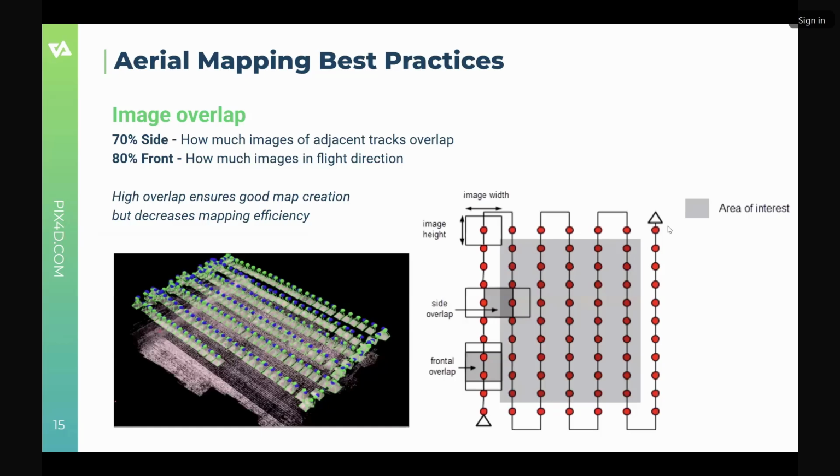So this is a really important parameter. It's the image overlap. Basically, if you want to stitch a map like we do, like what we call an HD map or an ortho mosaic, the images need overlap because, I mean, you can't really stitch something which has no overlap. So that is really important to get a good map. And there are two parameters. That's the front overlap. So it's when the drone flies in flight direction, the overlap of the individual images. And that's the side overlap.